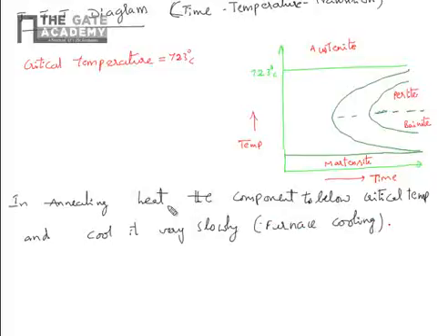In annealing, the objective is to relieve internal residual stresses. Because we are cooling very slowly, a fine crystal structure will form, which improves mechanical properties.